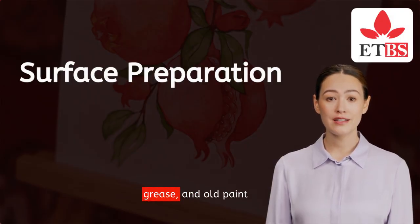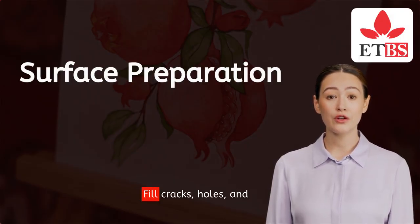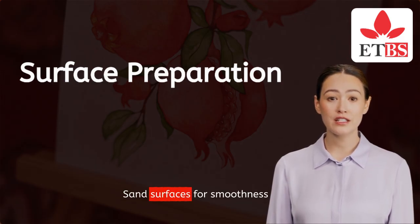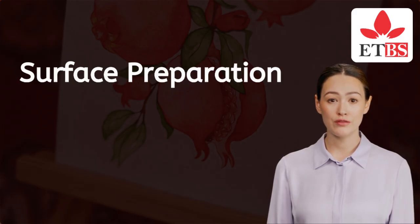1. Surface preparation, cleaning and repair. Remove dirt, grease, and old paint residues. Fill cracks, holes, and imperfections with putty or filler. Sand surfaces for smoothness and better paint adhesion.